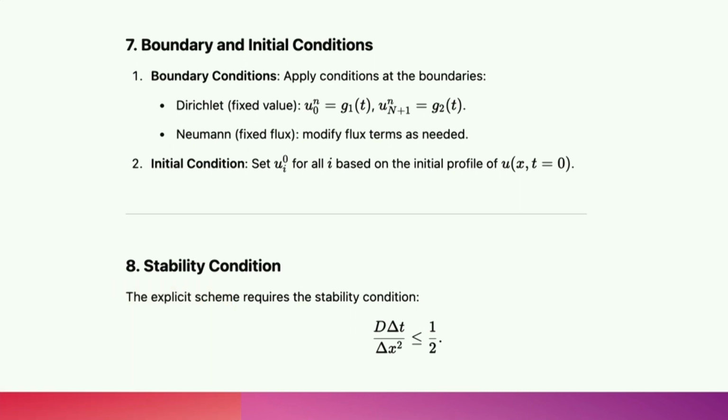Now, as in your previous lecture, you found that the stability condition is very important, because here we are using an explicit technique. There are two techniques he mentioned, right? Explicit and implicit. So we will be using explicit. And in the explicit technique, the time step is very important. So you have to maintain what value of time step you need to use. There is a number called CFL. The CFL number is a relation between the velocity, the mesh size, and the time step.